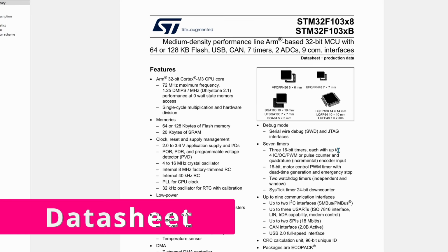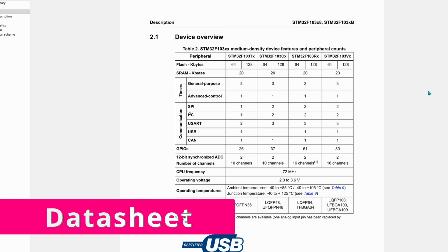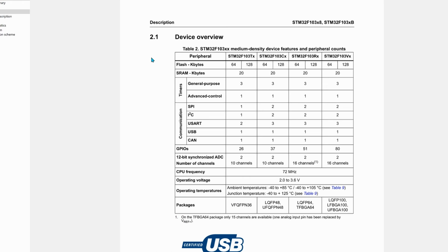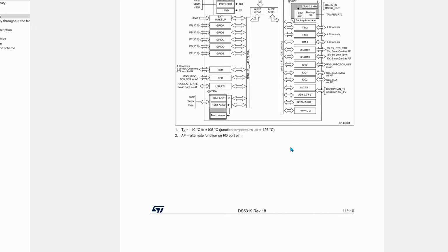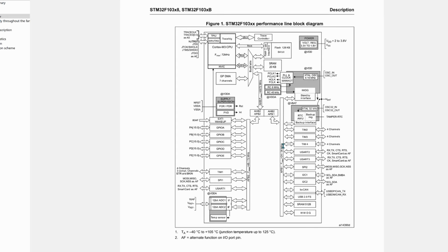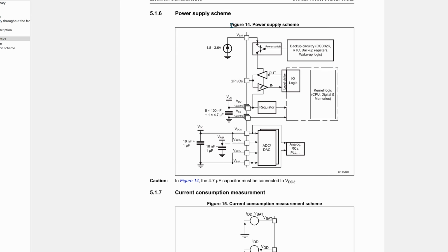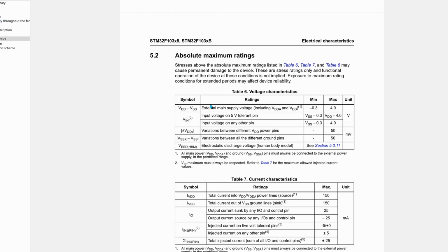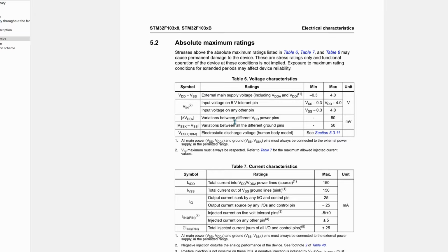The main developer document is the datasheet. It shows all the peripherals used, all of which can be viewed in CubeMX. There's a block diagram and clock system explaining the operating principles. There's a power supply diagram. When routing the boards, I used its recommendations for connecting capacitors and power supplies. There's a maximum power consumption table. You can imagine how long this chip will last on battery power.